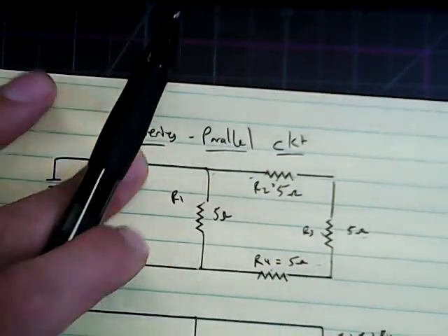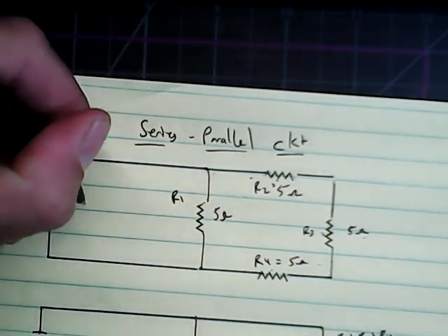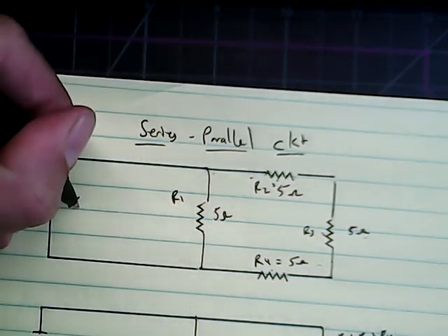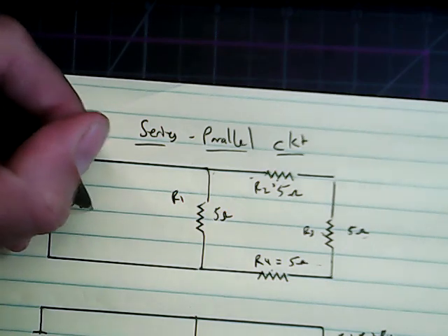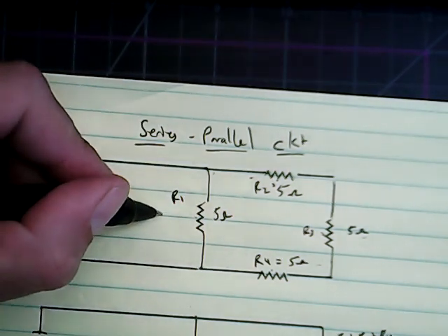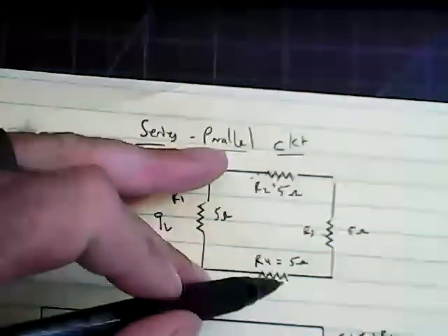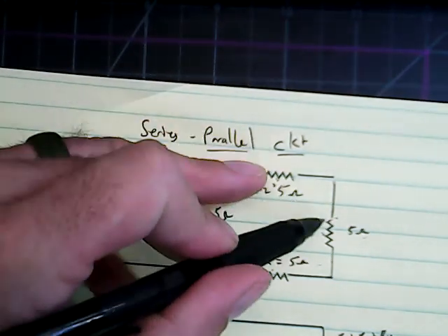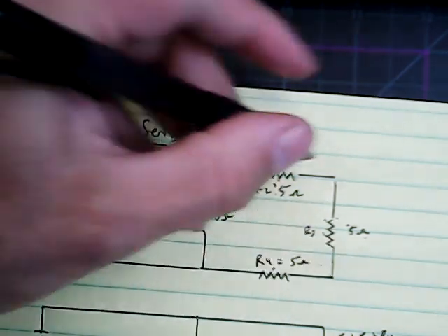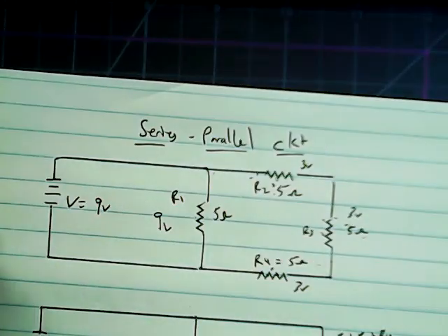So for example, if we go back up to the top view here, we remember when we were discussing voltage, if I had a voltage in this circuit of, let's just say 9 volts, that 9 volts would carry across R1, and then the combination of that 9 volts would get broken down throughout this. And these are all the same values, so in reality, that 9 volts would get broken up between 3 volts, 3 volts, 3 volts.